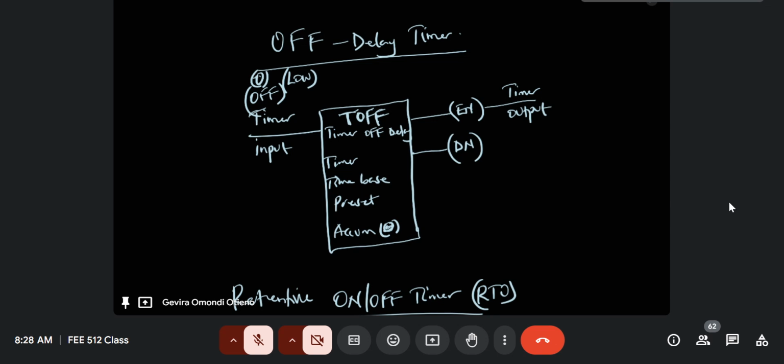Meaning, when we switch back on the timer, it will start afresh. So if the preset value was 10 seconds, and power went off when we were at 5, then when power comes back we have to go back to 0. And you see, time lost is never recovered.